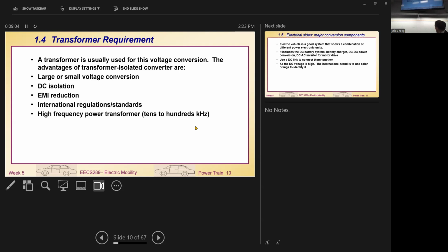So this kind of transformer is built internally into the converter. Converters have a transformer internally, and they are able to reduce the voltage. So that's how the technology works here. Of course, they are not using the big, huge silicon iron transformer. If you're using the charger or converter's internal transformer, we are using a really high frequency transformer, which is able to reduce the size by many times.